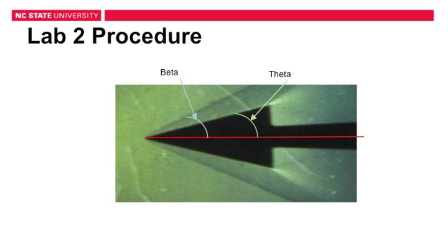The angle was found by importing the picture into SolidWorks. In order to account for any angularity in the flow, meaning that the flow is not parallel to the line of symmetry of the wedge, the angles between the shock boundary and the line of symmetry on the top and bottom were averaged. Although this introduces some amount of error, the angles were similar enough that it is negligible.